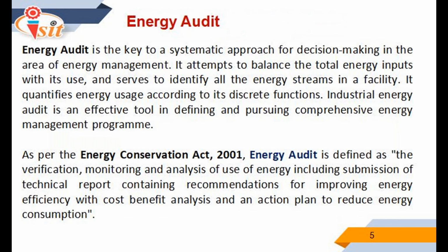Now, the energy audit, its types and methodology. The energy audit is the key to a systematic approach for decision making in the area of energy management. It attempts to balance the total energy input with its use and serves to identify all the energy streams in the facilities. It quantifies the energy usage according to discrete functions. Industry energy audit is an effective tool in identifying, defining and pursuing a comprehensive energy management program.